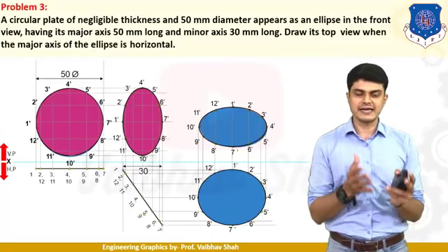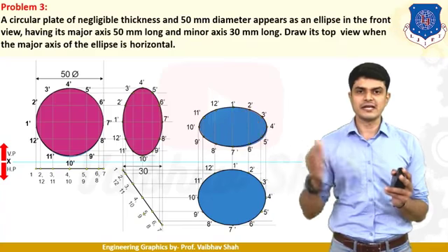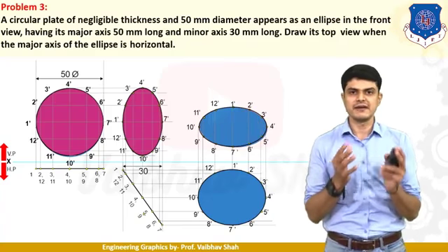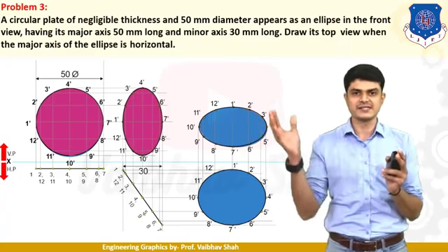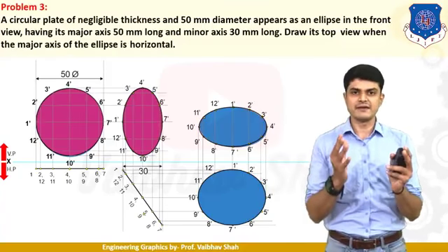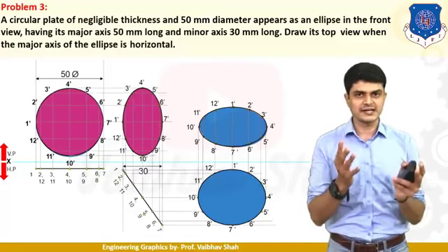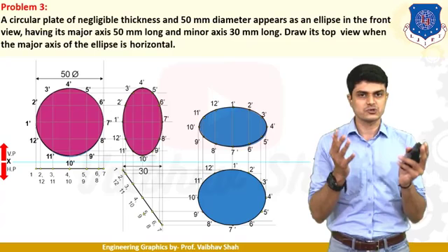After getting this point 7, let us draw a vertical line from this inclined line and a horizontal line from this first stage circle. We will have intersection points as 1 dash, 2 dash, 3 dash on this ellipse, and after getting these intersection points we will have all of the points on the ellipse generated. Just connect these points in order to get the ellipse drawn.